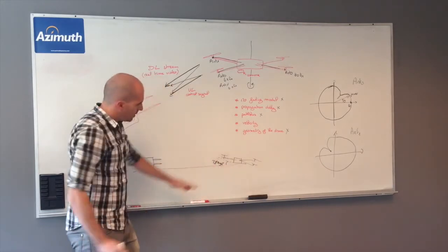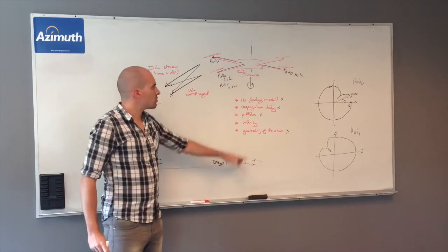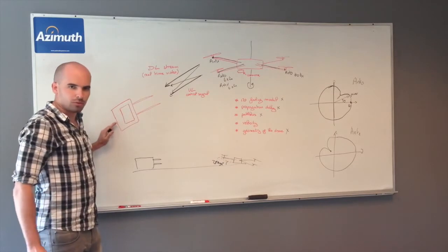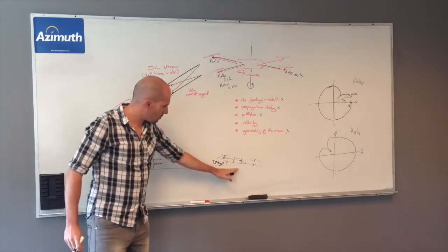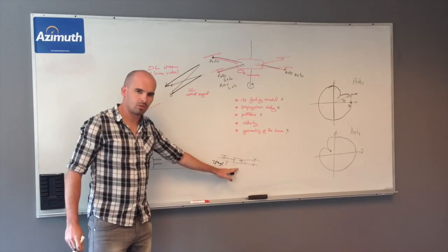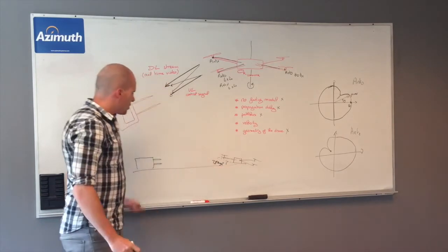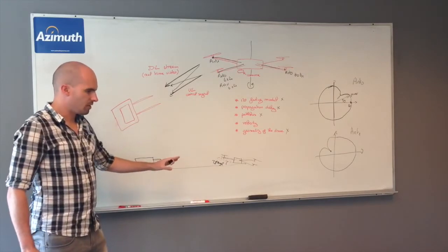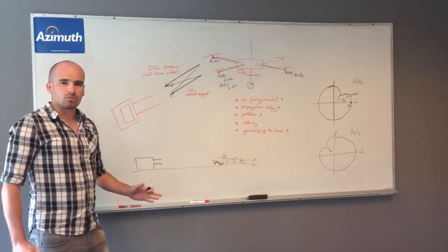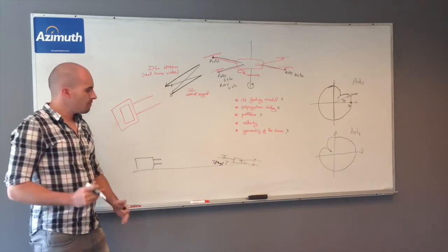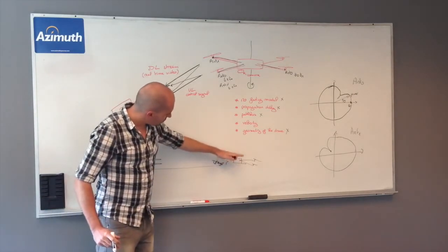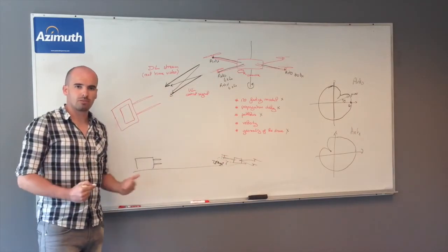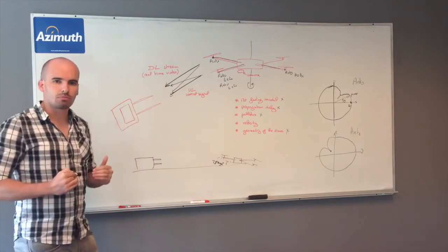So this is a tilt angle with the horizontal plane. This also has an incidence on the power that your drone will receive, and hence the power that your controller will receive. And this is also a hot topic for drone manufacturers and something they really need to test. This would be much more difficult to recreate on the field actually. The only way to do that would be to go again in the anechoic chamber and test the drone for different tilt angles. When they get those values, we can feed the channel emulator with a CSV file, getting all those power values.